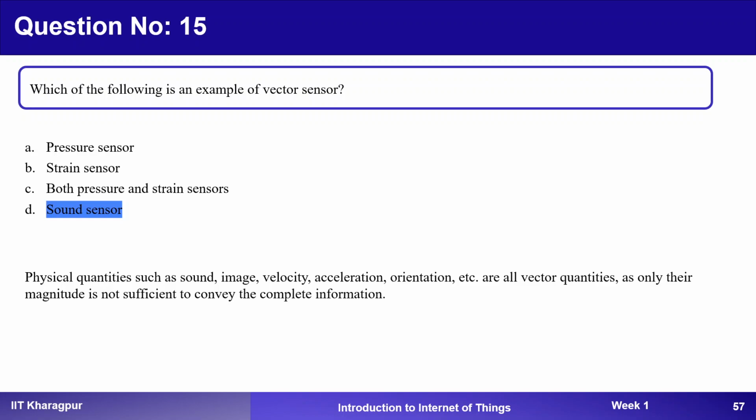Can you please repeat? Yeah, if the sensor is placed somewhere in the tank, and it needs to give you the pressure of the water, and as the water goes up, the pressure gets built up. See, for that you cannot use a pressure sensor. There are different sensors which are called liquid sensors, so in that application you have to use those. Pressure sensors are something where you put pressure on this point and it will detect the amount or magnitude of the pressure which is applied. Okay, so direction is irrelevant here. Yeah, direction is irrelevant in case of a pressure sensor. Thanks, madam.